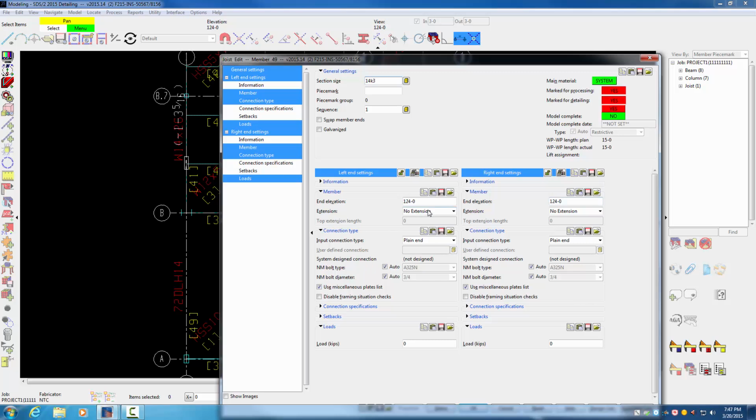and in this case here, this bar joist that we put in is at a column, and column bar joists need to be bolted down. So as you look on your sheet S2, at the intersection of A and 1 at elevation 124, you see on the west side of that column 2 dots along that bar joist. That indicates that them bar joists need to be bolted down.